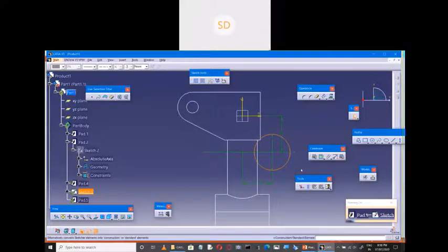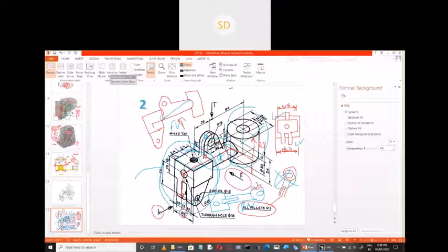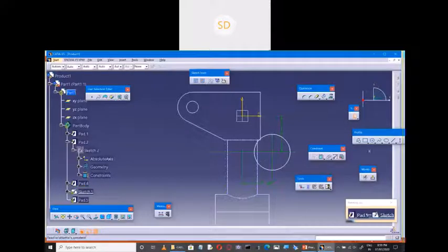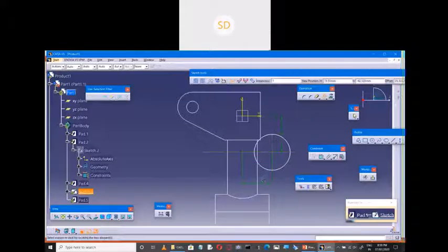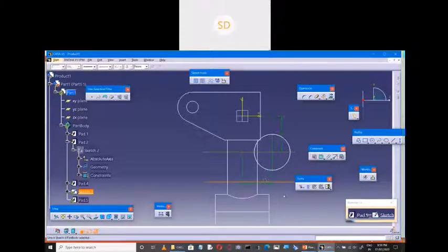Now this has to be not construction purpose. Okay, one more hole is there. It is of diameter 18 mm. So we'll see afterwards. I'll go for offset here. I will select this line. I will place it 30 mm downside.